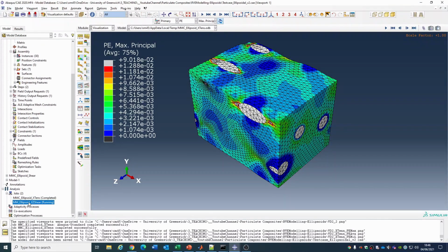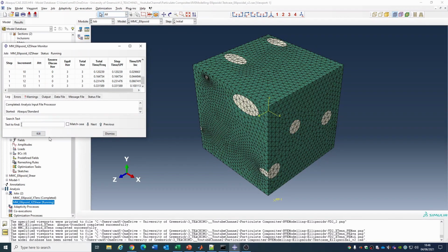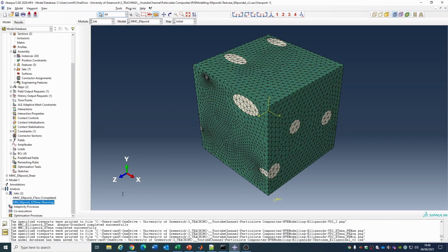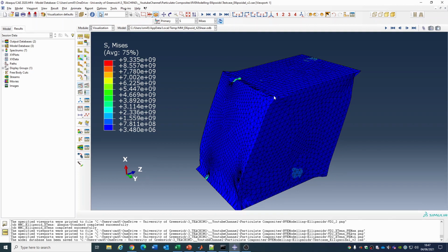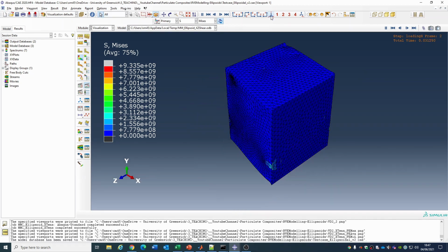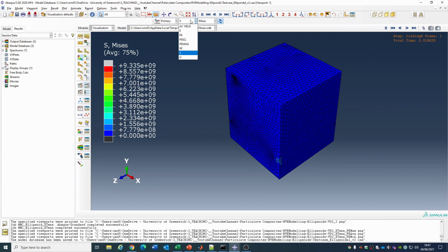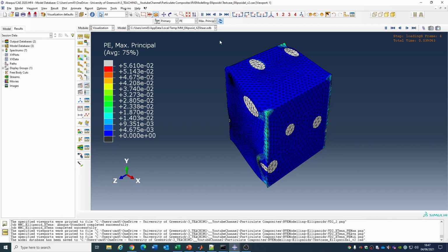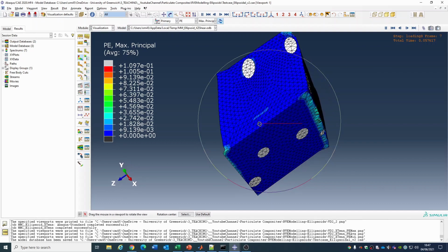So if we look at the ellipsoidal shear case, so if we monitor the result, it is still running, somewhere around 33% complete. So let's just have a quick look at the result. So for the shear case, you get a similar situation, XZ. So X in the Z direction is what we're seeing. So if we go back to the original position, okay, so this is the XZ phase, so it's shearing in this direction. Okay, so we could look at the plastic strain as well, and you get again an interesting result like what we've been showing.